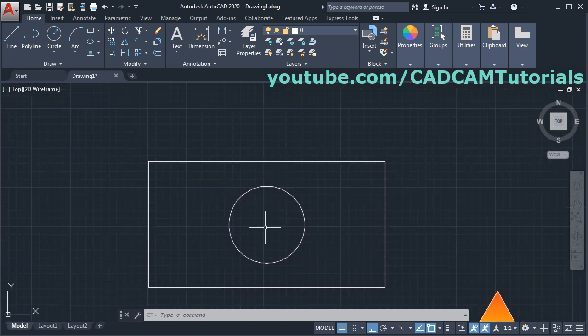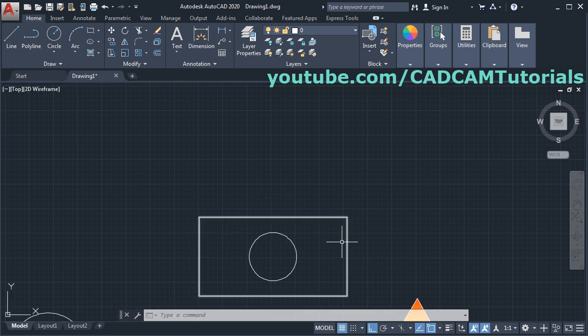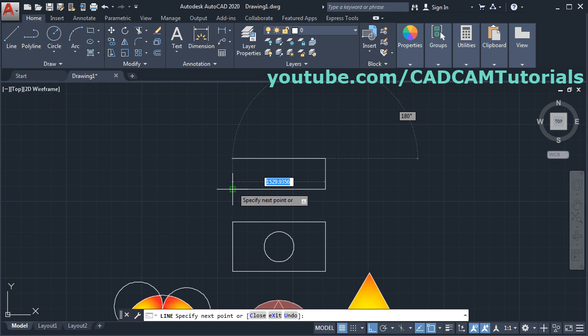So this object snap tracking is also very useful to create projected views. Suppose this is a top view and using this top view I want to create a front view. Then how to create that? Click on line, then take your cursor to this endpoint and take it away and click. Now the length of this line will be the same as the length of this line. Take your cursor to this endpoint, take it above and click. Then take it above, give the length, enter. Then again take your cursor to this endpoint, take it above and click. Click on this endpoint, enter.